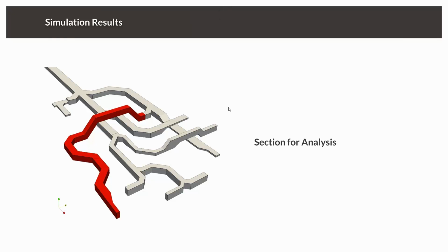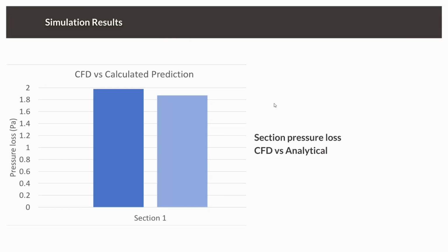And a big challenge in the past was that simulation was not available and people needed a way to determine the performance of HVAC systems which are made out of segments. And one thing you usually do is you use an analytic model where you're describing every section by section using a cross section and stuff like that. And usually this is not very precise. We are talking about up to 10% difference. And here CFD is able to provide you with a much better idea of the flow values.